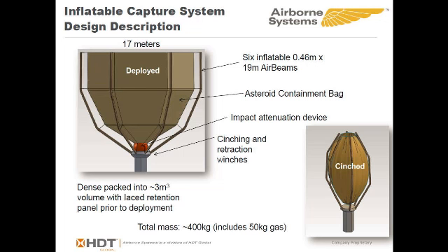We would envelop, and in that process, these beams probably would buckle. And that's why I kind of pointed that out, that in the right-hand corner picture there in the cinch configuration, you would have some buckling and compliance of the structure, but it would be able to tailor itself to fit the asteroid and be able to take the load that would be imparted in it. It could be torsional or lateral loads, and once that momentum is transferred to the spacecraft, the system would sort of realign itself and center the asteroid to the spacecraft.